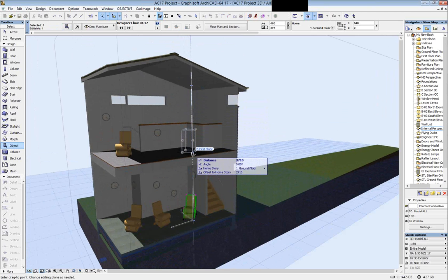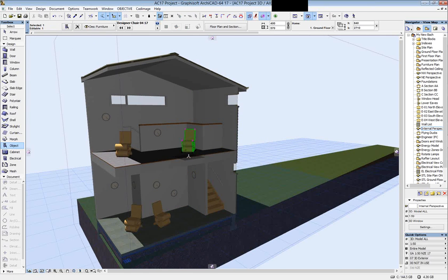If I click on those, I can accurately move this chair from the ground floor to the first floor, which of course is changing its home story. So now its home story is the first floor, excuse me. A lot of reasons we thought this would be quite good. Multi-story buildings which have a bunch of sun shading devices: select them, copy multiple from story to story to story. There can be many uses for this: floor joists, double T's, anything like that. So very powerful 3D story snapping.